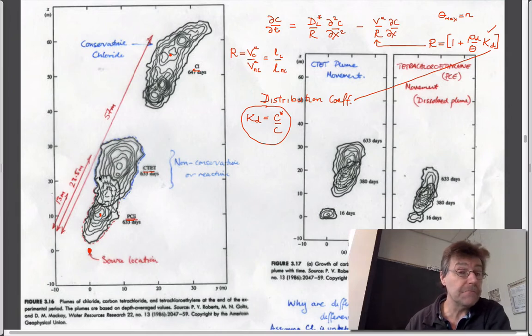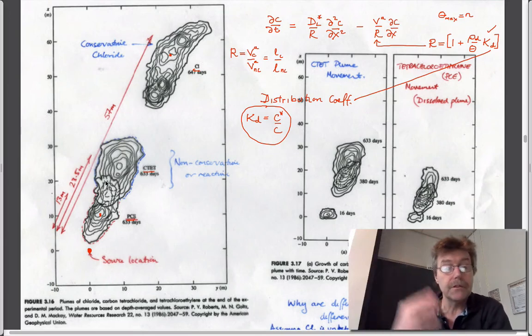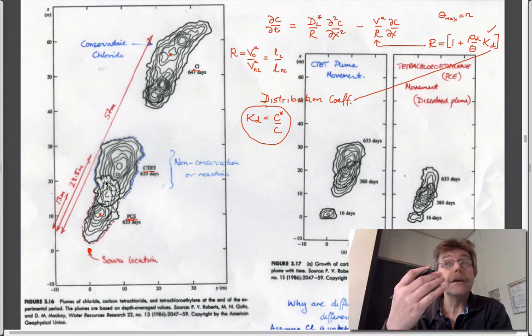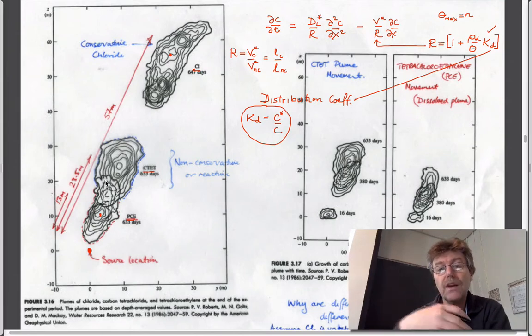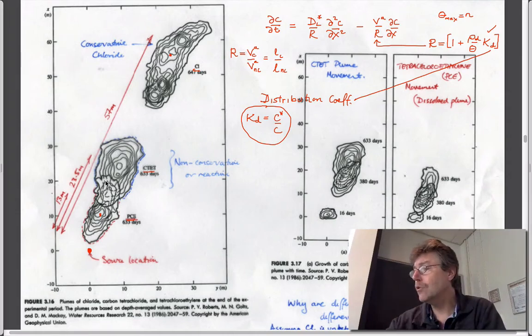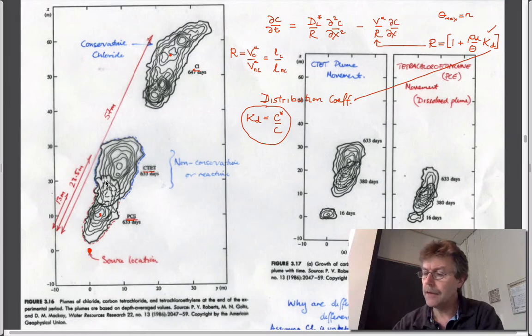So this is no different. I don't know if you still do it in high school, the experiment where you take filter paper and you dip it into a solution, maybe chlorophyll, and it separates the chemicals as it goes up. So it's chromatographic separation. It's really exactly the same process that's going on here, except it's in an aquifer, and instead of the filter paper being the medium which wicks this stuff and pulls some out into solution, it's actually the aquifer that does it. And so that's what our interest is, in being able to do that.